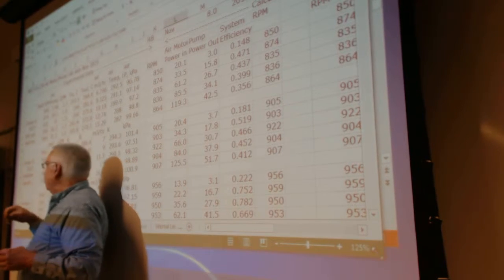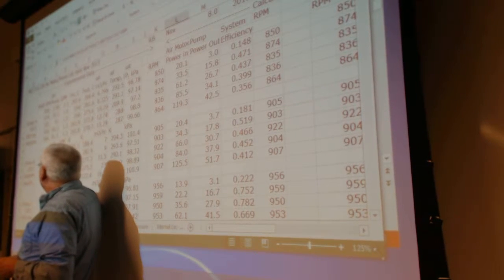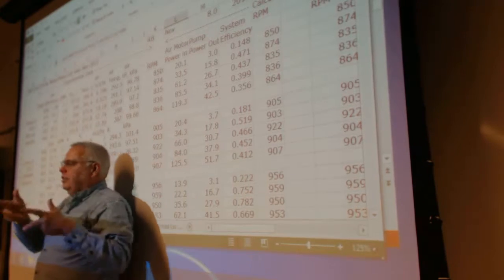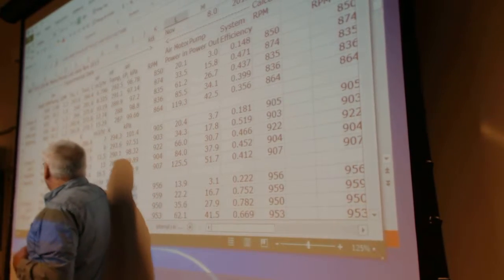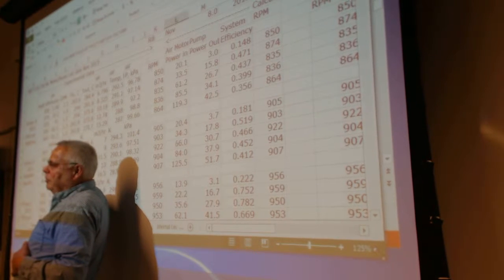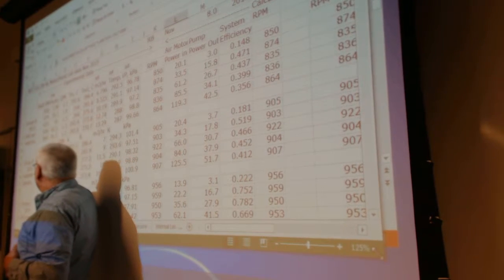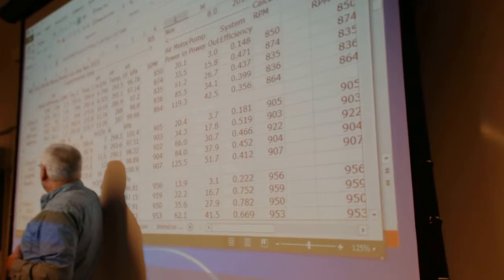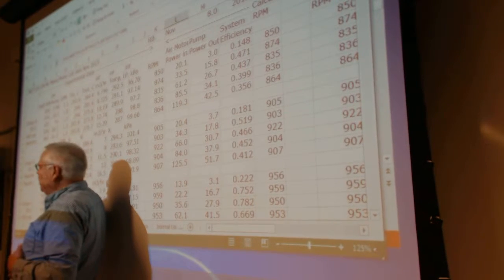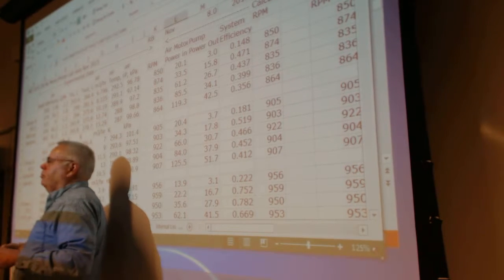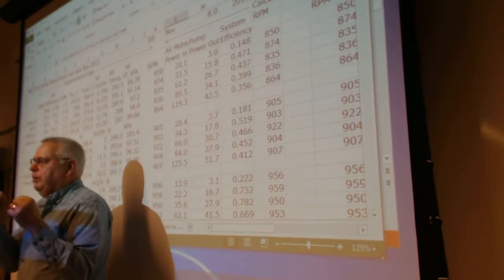And that's why your efficiency down here was poor, because all the friction in the system was eating up your power. And when you got up to here, suddenly you had most of the fluid going forward, and it's actually doing some work, but you don't have so much leakage. So your highest efficiency is somewhere in here, and then it started tapering off because you're putting the work into pushing the fluid forward, and it's squirting back around.